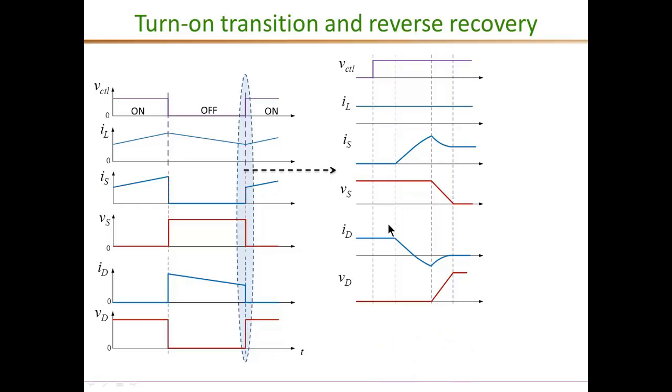During the duration when the diode current is conducting up to this peak negative current, the diode voltage is close to 0, and therefore the switch voltage is at its rated value. Only after this reverse recovery process can the switch voltage begin to fall, and so clearly we have an overlap of large current and full rated voltage during both this current rising interval and this voltage falling interval, once again resulting in very high instantaneous turn on switching losses.